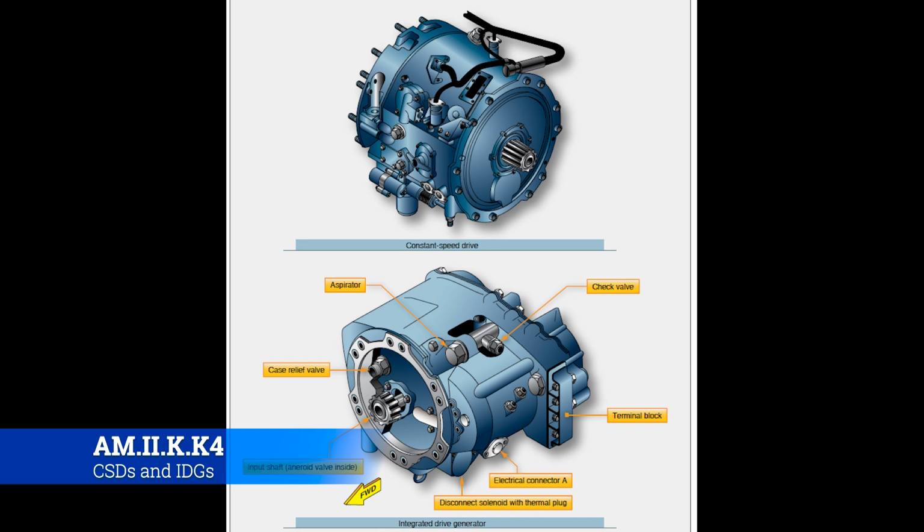So aircraft AC alternators should always produce a frequency of approximately 400 hertz. If the frequency strays more than 10% from that value, the electrical systems don't operate correctly. You get all kinds of erroneous problems that, as a troubleshooter, you're going to start chasing your tail over, because the problem you're chasing is actually not the symptom that's manifesting.